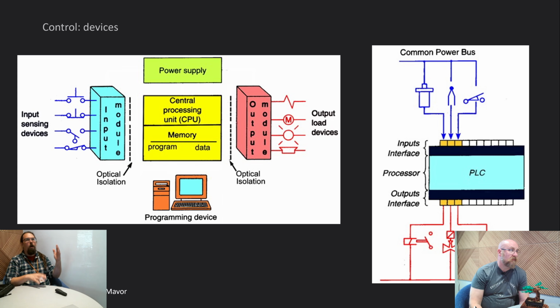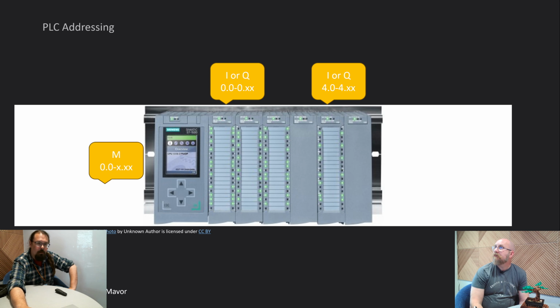And so that might be optical isolation. I think that's the common solution today. It's optical, yeah. But older modules might use different methods for doing voltage protection. Yeah. And that's to protect the PLC from overcurrent and overvoltage events that could happen in the industrial environment. Yeah. So that the PLC doesn't die, only the module dies at worst case.